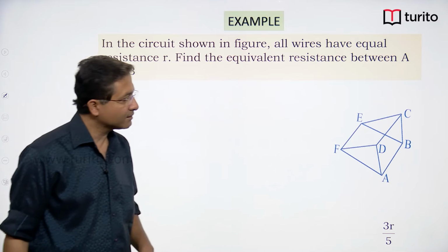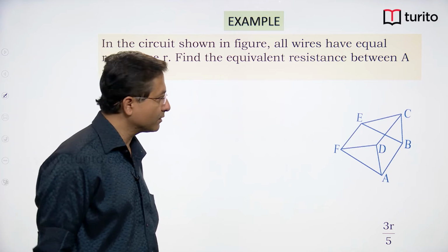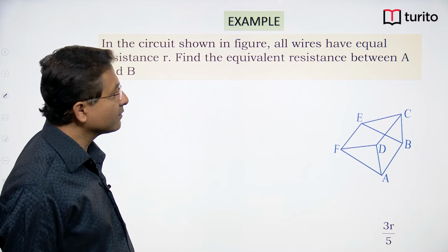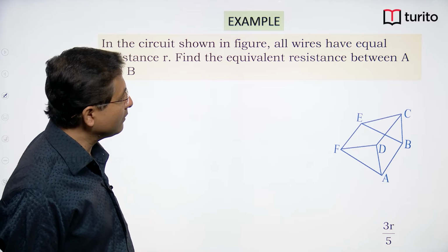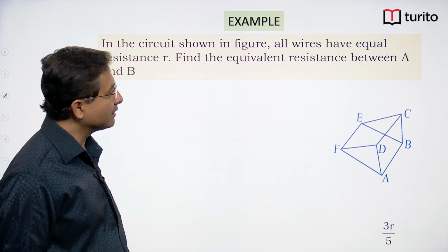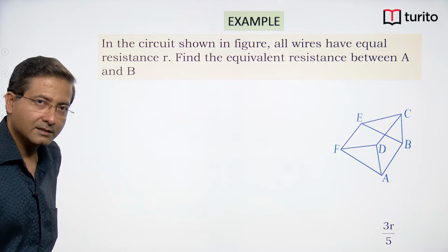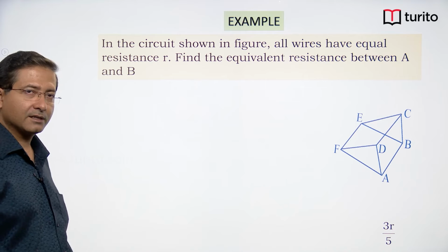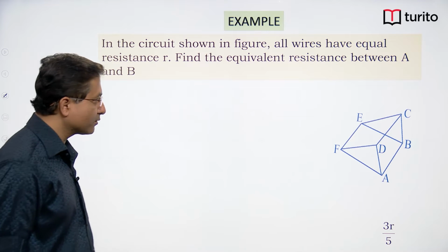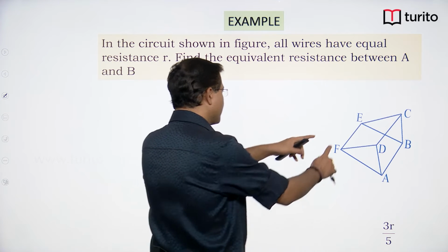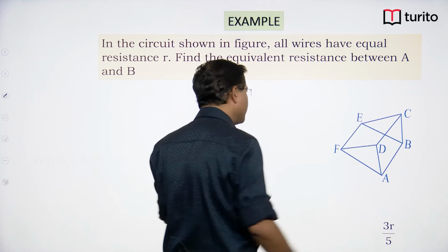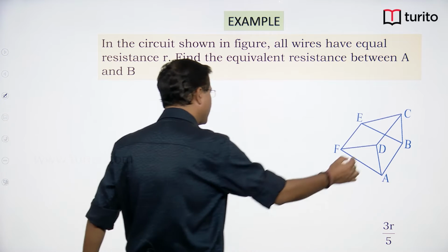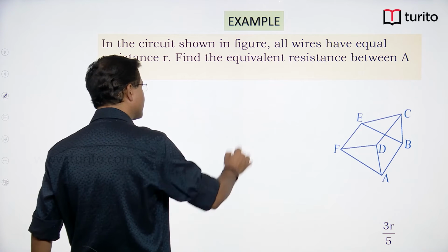Across AF it is a little difficult to decide. So what we can do, we can convert this 3D into a 2-dimensional diagram. Otherwise you can directly see that there is input output symmetry. So what I will do, I will stretch the front one and place it over the back one. So this front one I am stretching, this triangle I am stretching.